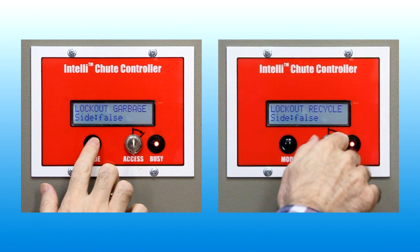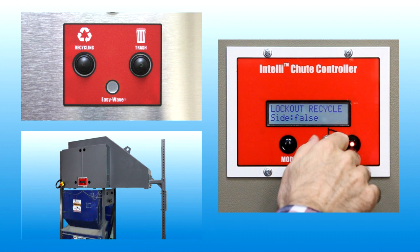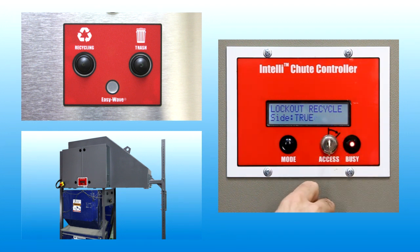The lockout side parameters allow the BiSorter to continue operating in a semi-functional state during some exceptional circumstances. For example, in the case of a new construction building, trash compactors might be installed before recycling equipment is available. By activating the Lockout Recycle Side configuration, the chute system can be put into temporary service as a single waste stream trash chute.